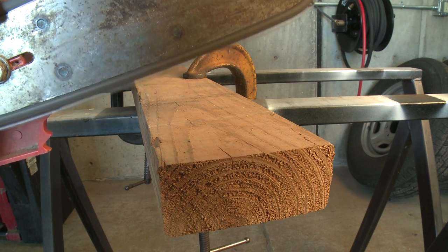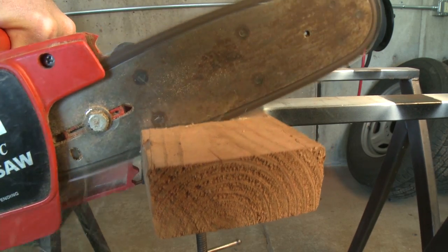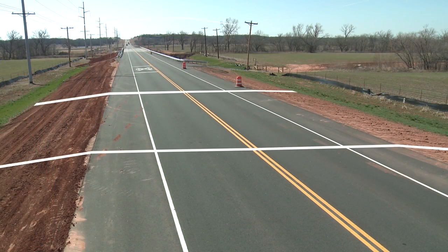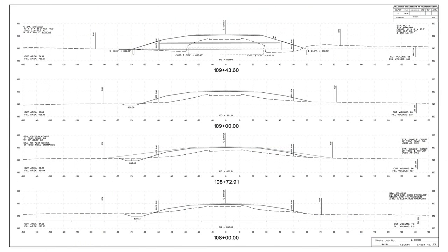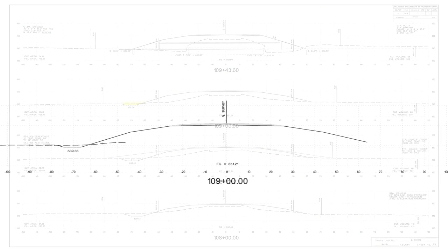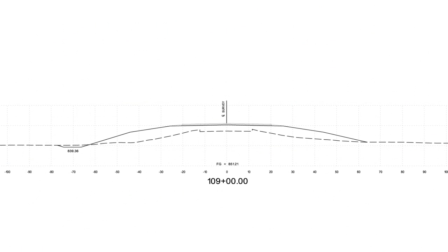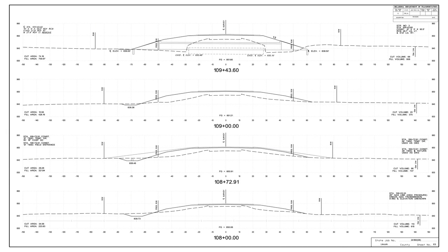If we take a look back at our 2x4, if the typical is the template of the front view, the cross-sections are the slices of the road at even increments along the project. They depict how the typical section will interact with the horizontal, vertical alignments and existing ground. They also call out any changes to the typical design. This gives the reader a better look at what is actually happening throughout the project.